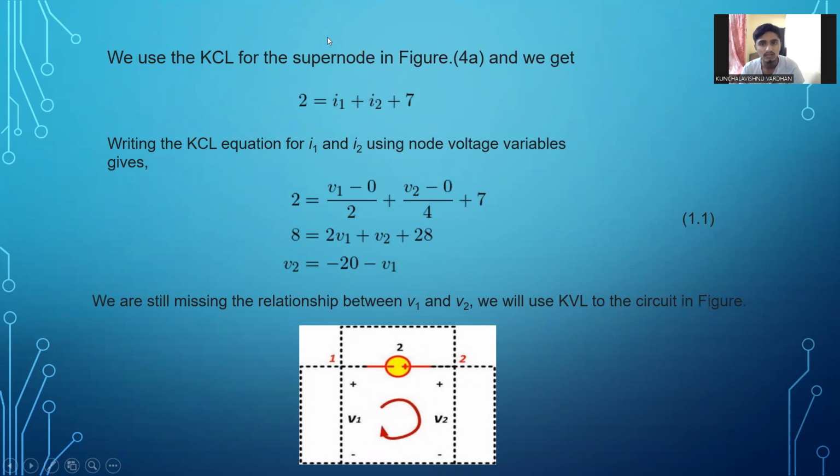We will use KCL for the supernode. We get 2 equal to I1 plus I2 plus 7. Writing the KCL equation for I1 and I2 using node voltage variables gives 2 equal to (V1 minus 0)/2 plus (V2 minus 0)/4 plus 7, because both are connected to ground.